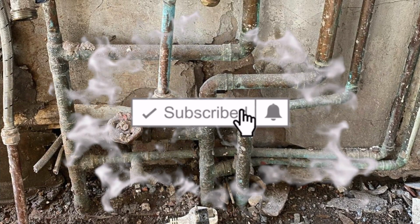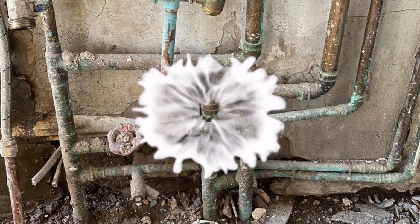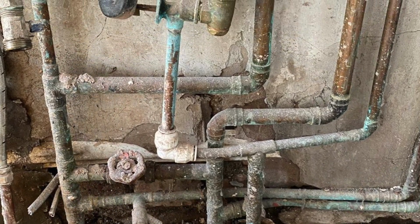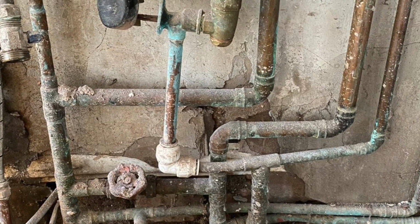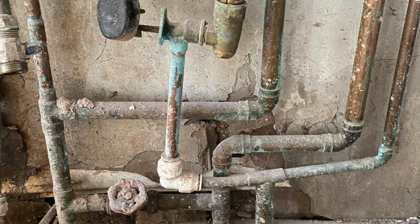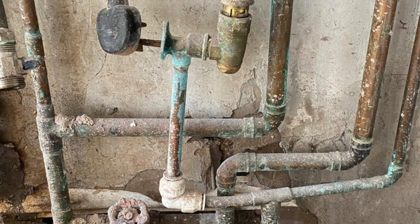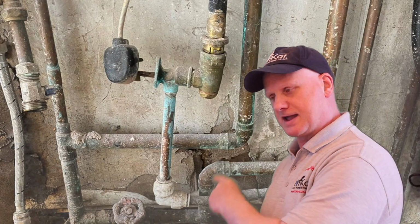Now, this first picture represents you going to a site where they're doing some renovations, and you find this in the kitchen where they're asking you to install a new boiler. So, what do you think about this one then? What have we got here? We've got a plastic push fit fitting on a gas pipe leading up to a bayonet feeding a cooker, and the cooker is still working.